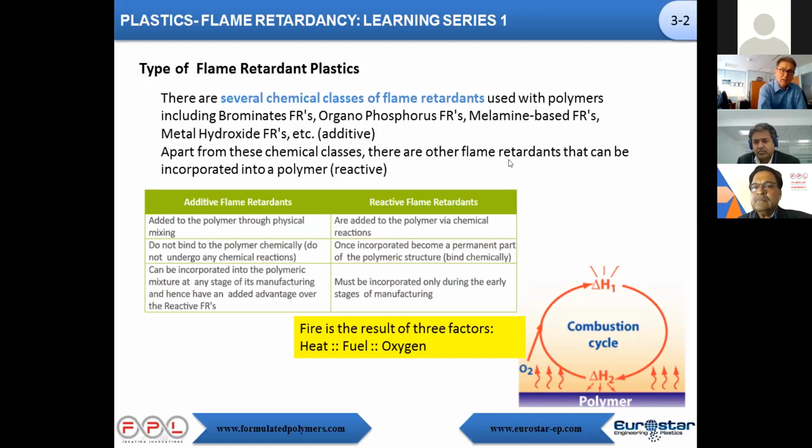And it changes our life, because from time to time, you just need a few percent of flame retardant. But sometimes, for example, for transportation or for tunnels, you need to add more than 50% flame retardant in your plastics, meaning that it changes completely the behavior of a plastic, the properties of your plastics.